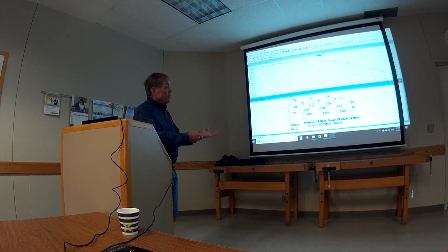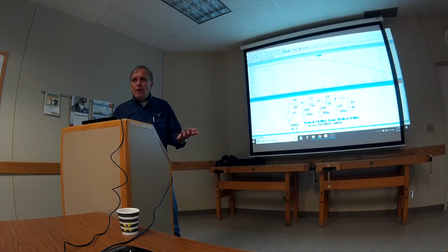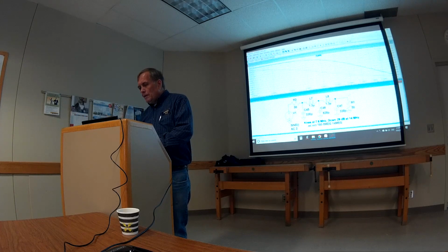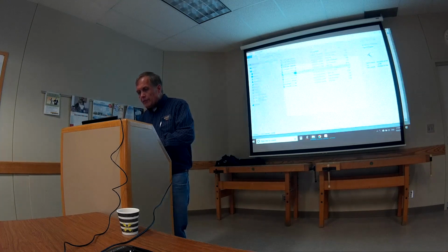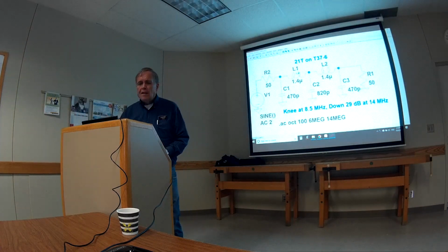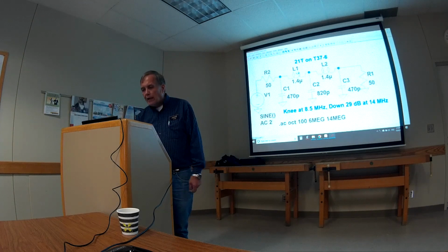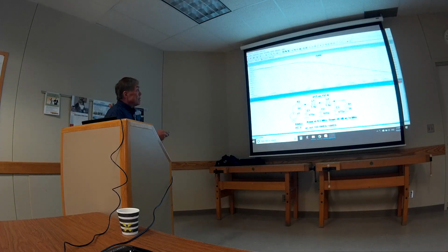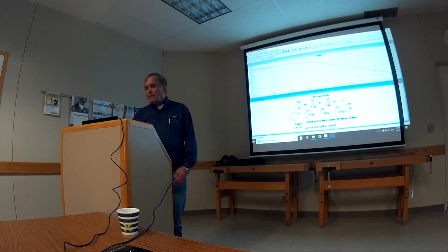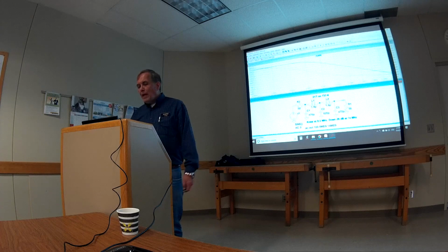You can type in, you can change values, you can see what it would look like. How much suppression will I get if I use those values for it? I'm going to just show you the K1, the Elecraft early one. Mert's got one, I've got one. It's a little more advanced. It's got a digital display on it and everything. They've improved this one a bit. Once again, the knee is about, well, it's all the way up to 7.6 or something, which is fine. And at 14 megahertz, it's about 30 dB. So it's not quite there, but it's not bad. 29 dB.